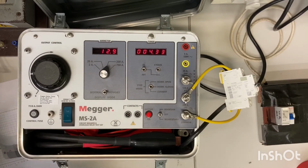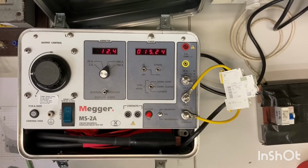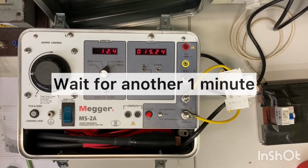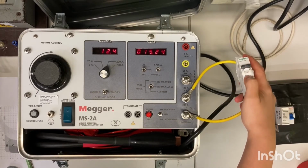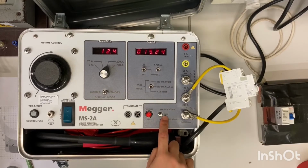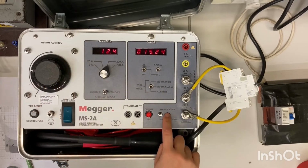You can see that this time the current value has been increased to around 12 to 13 amp. And after that, we have to wait until the MCB trips. So we just heard the click sound and the MCB has been tripped. So once again, back to off position, and we have to record down the data and wait for 1 minute. After the MCB is cooled down, we can try a larger current value. And for larger current values, the disconnection time would be shorter and shorter.